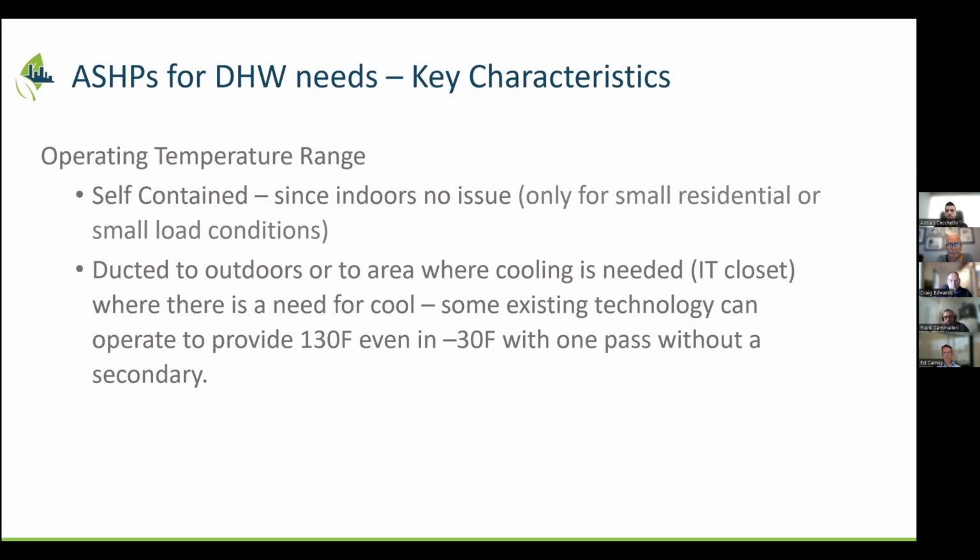I'll also say that it's one of the easiest applications, as you said. I'll confirm that because with one heat pump, you can literally go, because of the cold incoming water, we're able to take that refrigeration system and raise the temperature all the way up to usable temperatures around 130. No, that's great. Thanks for clarifying that. Yeah, that makes sense. Again, as larger applications, you really have to be mindful of where the cooling is going, and you can run into issues obviously in mechanical rooms where you're somewhat limited.